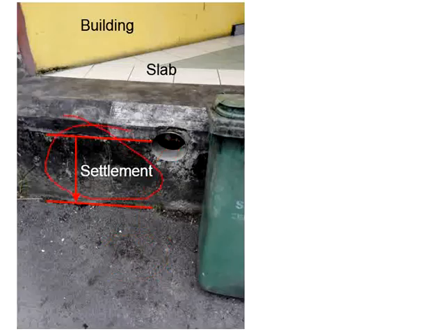Now that because of the settlement, it is nearly impossible for the water from the roads to be discharged into the drain. Ultimately, the drain here becomes redundant. Now, what leads to these conditions? The main reason is that the buildings are constructed over deep foundations. Specifically, we are talking about pile foundations. However, the roads are constructed directly onto the ground. Over the years, settlement occurs year by year.